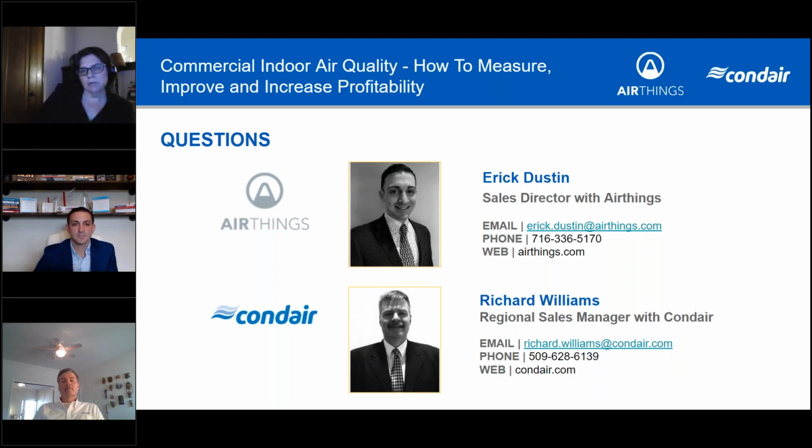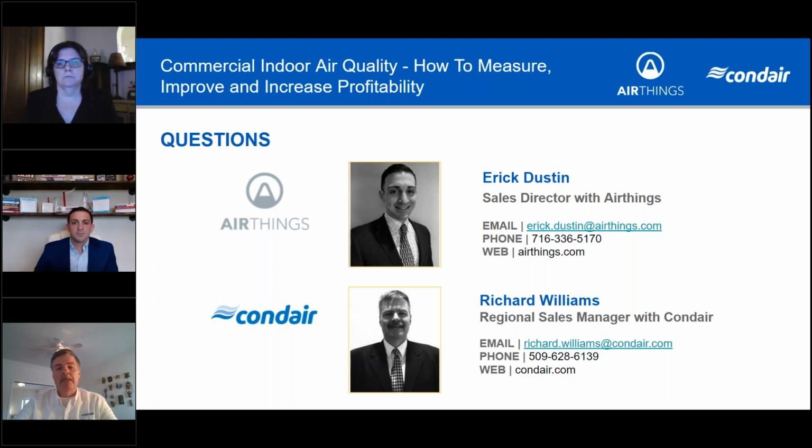Okay, and it looks like we got one more question for you, Rick. How is each zone controlled? With the direct humidification system, again, it is designed to handle a very large space, areas that can be hundreds of thousands of square feet. So on the pump skid, or kind of where all the magic happens, is a PLC controller. And from there, we run a humidistat out into each space or each zone so that we're able to get real-time feedback on the humidification level in the room.